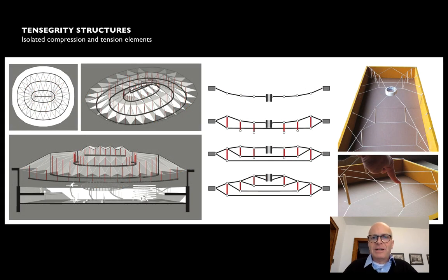One kind of exotic combination of form-active elements and vector-active elements is what's called tensegrity. This basically uses straight cables, which go in vertical and horizontal directions, to accommodate gravity loads by separating, just like a truss does, those loads into tension and compression elements, and then using the network principle of vector-active systems to carry those loads to anchorages on the sides of the span.